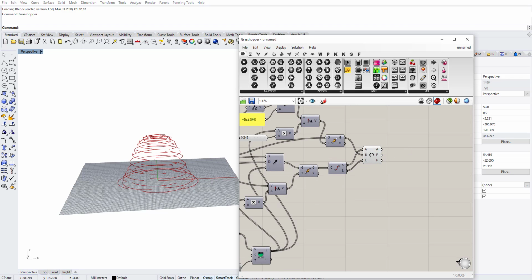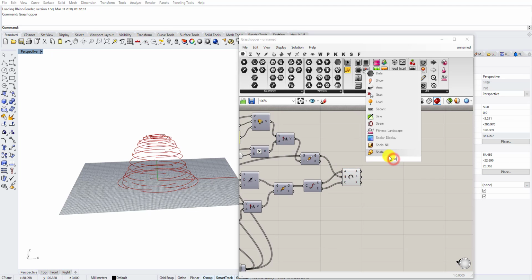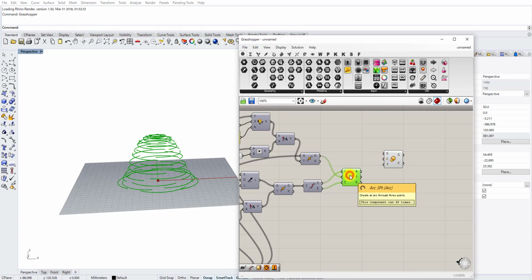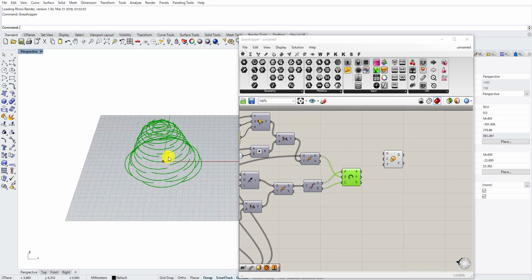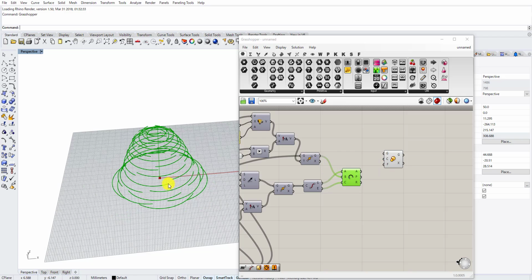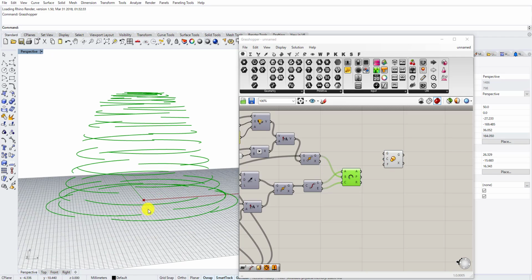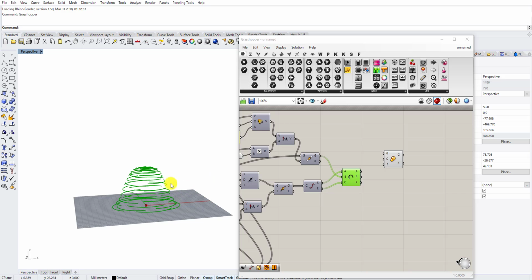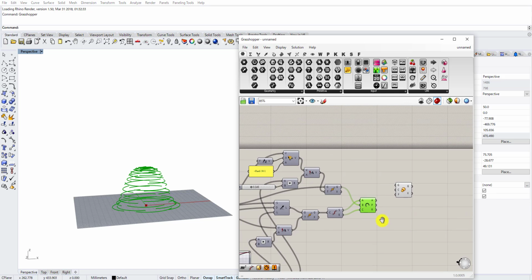Okay. Now from this one, what I could do to make it like a rose, I could move this base curve with the scale from somewhere around the center to go outside and make a loft to actually make a leaf.